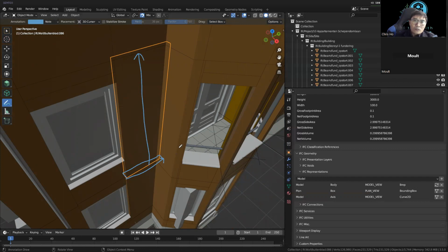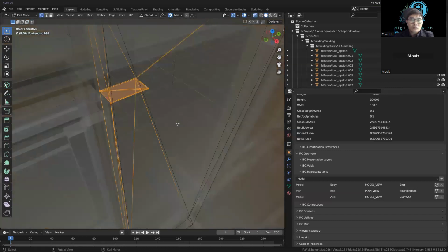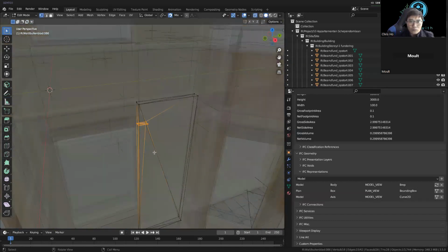There are many types of geometry in our industry. You might have heard of meshes, and you might have heard of NURBS, for example. By far the most common geometry used in our industry are solids, which are things like simple extrusions. Whereas this wall is represented using a BREP, which means I would be editing it in this form. And you can see that this wall actually has this weird slice in it. That's just the way ArchiCAD has given it to you.